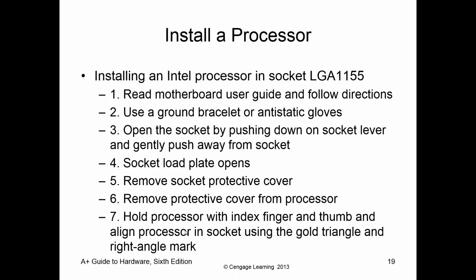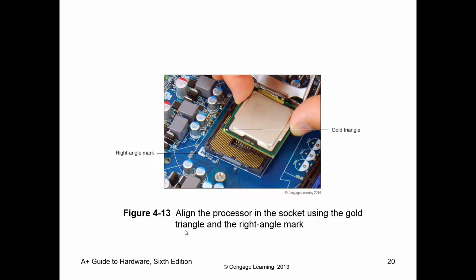the markers on the processor line up to the socket. For example, with this motherboard, we have an arrow, and there's an arrow denoting on the socket bottom left-hand corner. That way you can verify that those parts are lining up. There's also notches on the side that prevent you from installing this incorrectly.